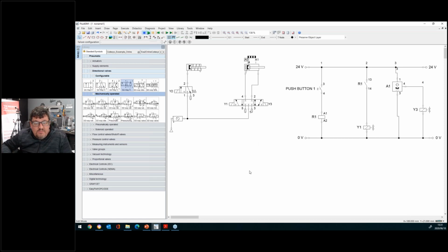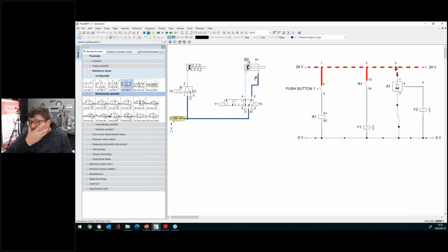That 5/3-way valve depends on the signal. Let me quickly go to your simulation package. The moment I press this, it will go to that position and it will go back. But if you wanted to be in the mid position, guys, the mid position will determine in which position your actuator will stop. If I give it a signal currently, because I'm using it as a control now, I will change my control circuit in such a way that I will only give a pulse, and it must go to the mid position, look there. It will then stop in the middle, because I'm actually not controlling it correctly now. But you will utilize a 5/3-way valve to determine the position where you want to stop it.